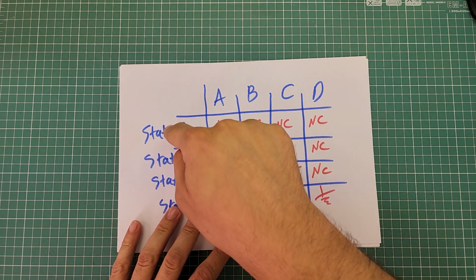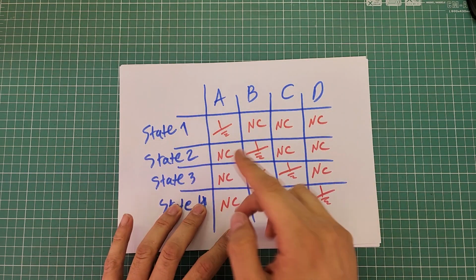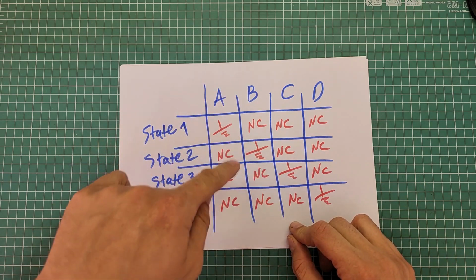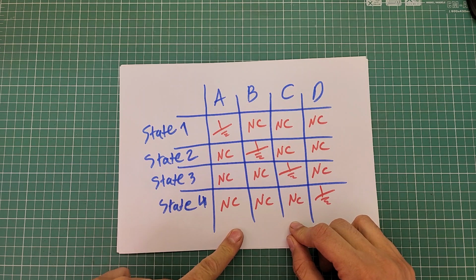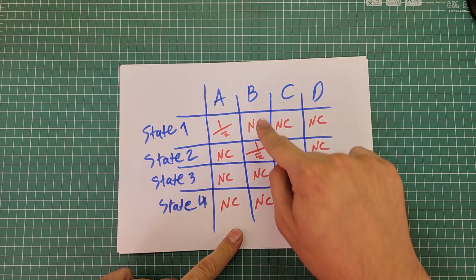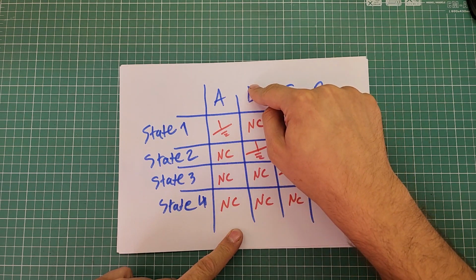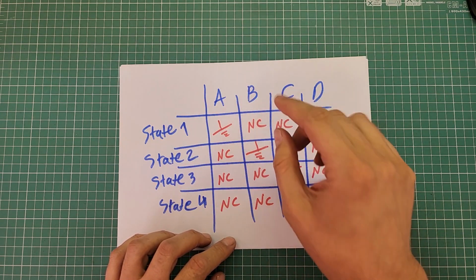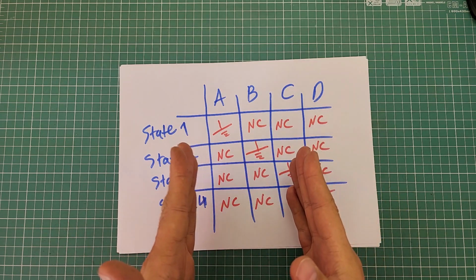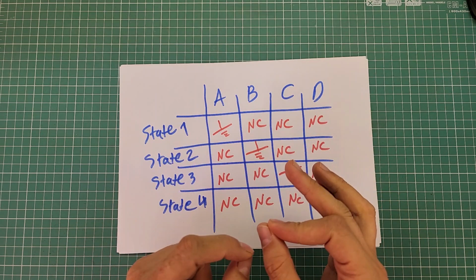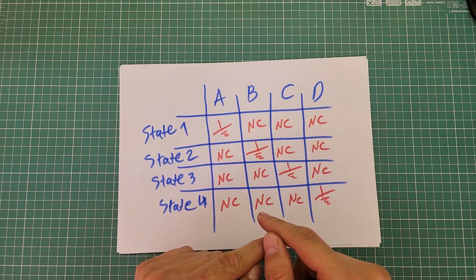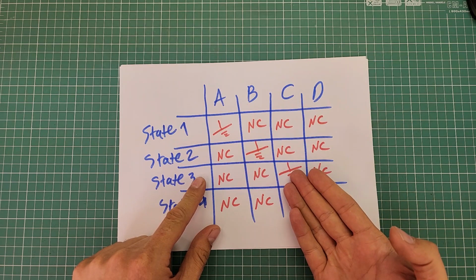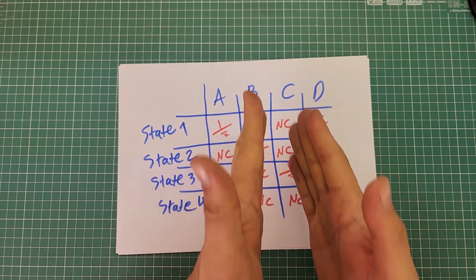So if you want to go from state 1 to state 2 in microstepping, you have to decrease the PWM on winding A to 0 gradually. At the same time, increase the PWM on winding B from 0 to 100%. When the PWM on winding B reaches 100%, it means that the step is completed and you have to take the next step. Next step is to go from state 2 to state 3, where the winding C is active. So the similar thing will happen here.